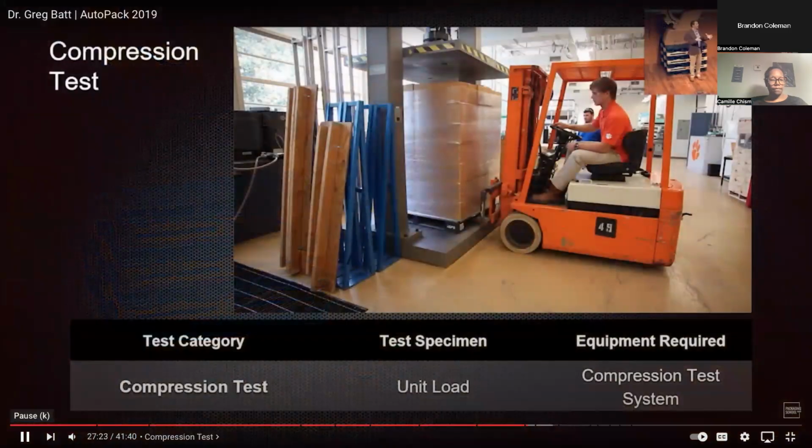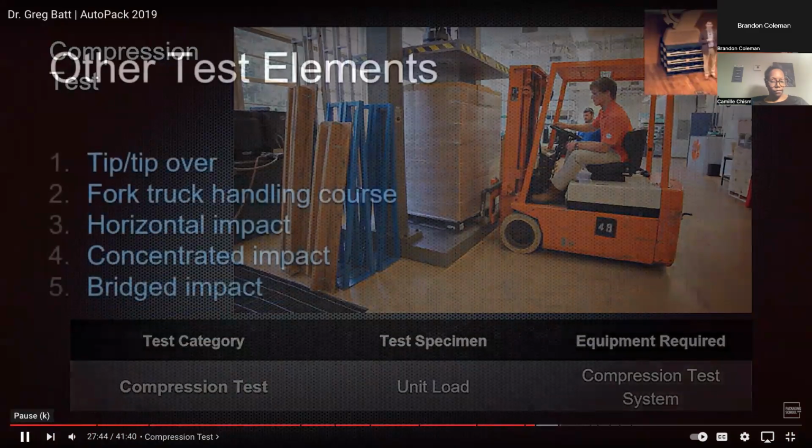at equilibrium with. Often it could be standard conditions, that's fine, 23 degrees Celsius, 50% relative humidity, but there might be interest in us testing at really high temperature, high humidity. It was nice out here this morning. A week ago, it's not so nice, it was hot and humid. And our packaged products go through this environment, and it has a big influence on our compression performance.